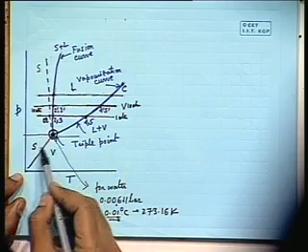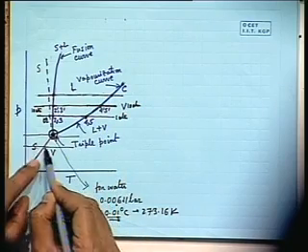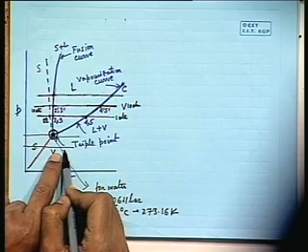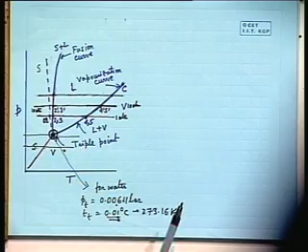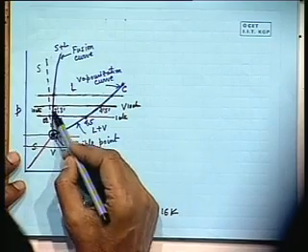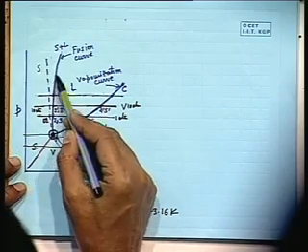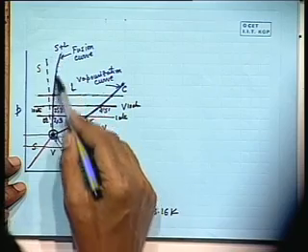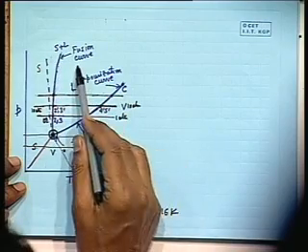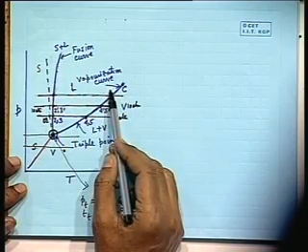So below this pressure, if you heat solid water, it will directly transfer into vapor. This process is known as sublimation. Therefore you see the saturation states in the PT diagram appear as points, and the locus of those points are known as saturation curves. Fusion curve, this is the vaporization curve.